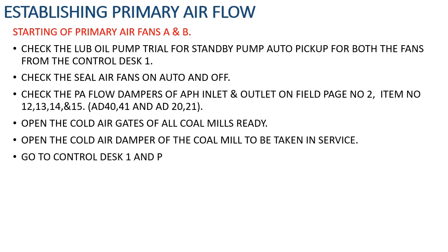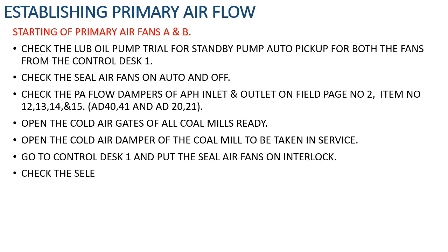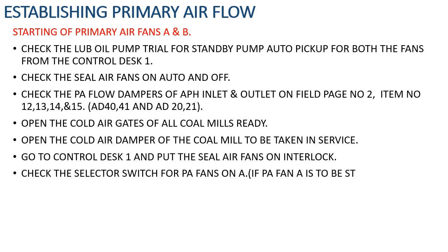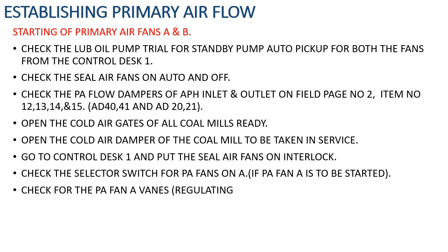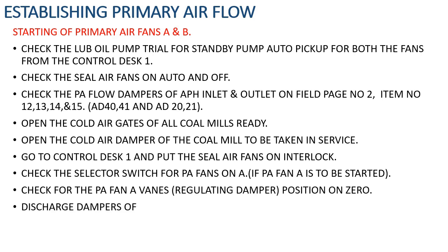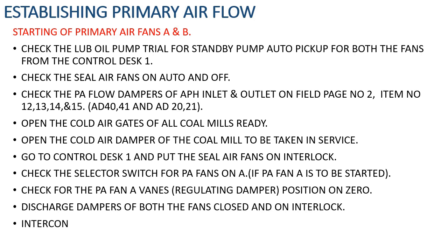Check the PA flow dampers of APH inlet and outlet on field page number 2, item numbers 12, 13, 14 and 15, that is AD 40, 41 and AD 20, 21. Open the cold air gates of all coal mills which are ready. Open the cold air damper of the coal mill that is to be taken in service.